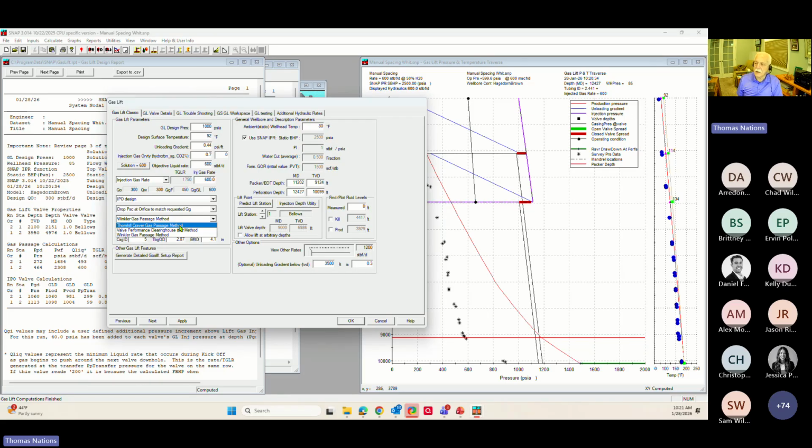Gas lift valves have flow passing through them that is not through a square-edged orifice, but the main thing is that the ball and seat in a live gas lift valve, the ball is never very far off seat, typically only about 40 thousandths of an inch of lift off the seating surface.